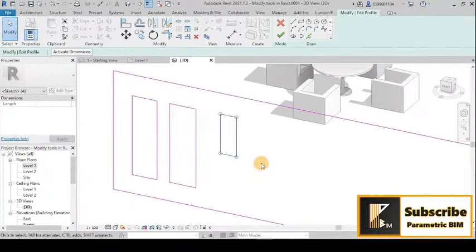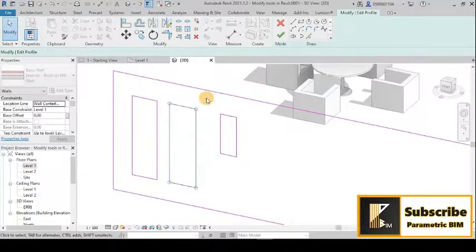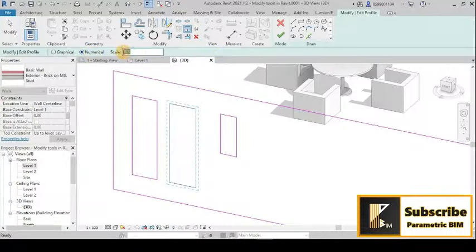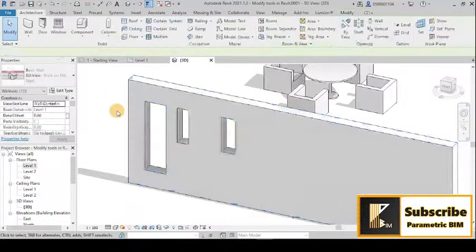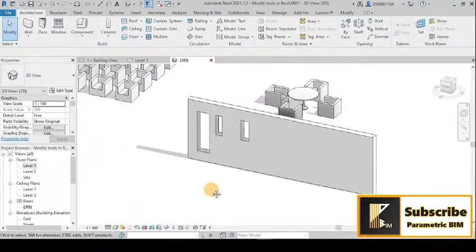So this is the graphical, but if I want to make, for example, scale of the here by numerical and I know the proportion, maybe I want to make it by half, so I will click the base point and it will automatically make it like that. Also, you can bring any image, and in the same way you can scale it. So this is some applications of scale.